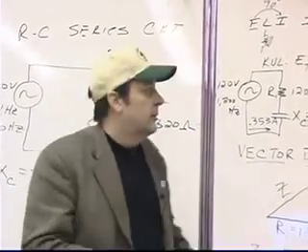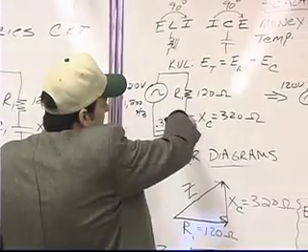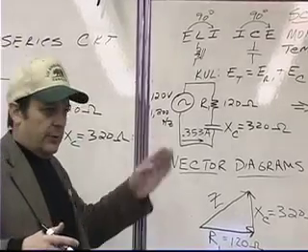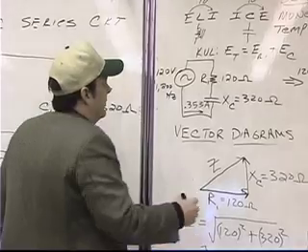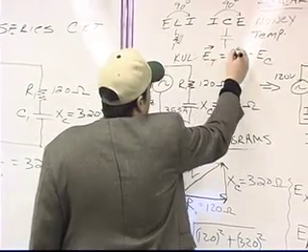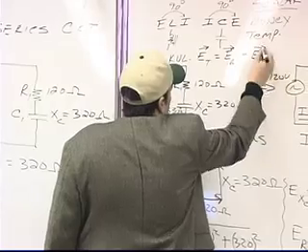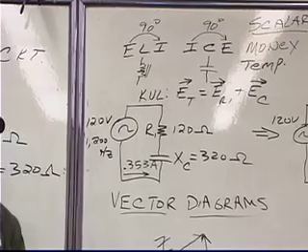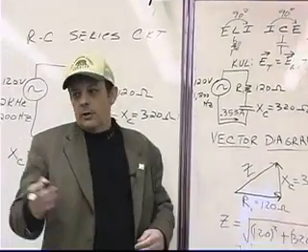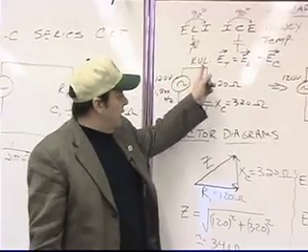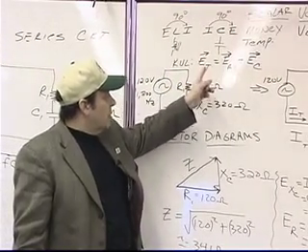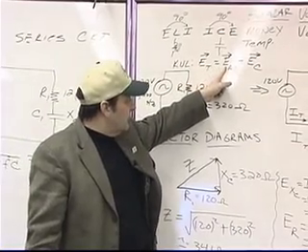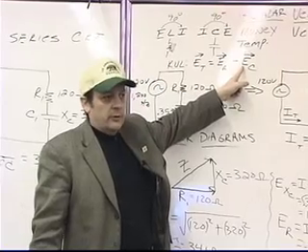That's adding algebraically. When we're dealing with RC circuits where we have an out-of-phase condition, which we see on the oscilloscope that I erased, but I drew in the beginning of the lecture, okay? These have to be considered as what we call vector quantities. And by putting a little arrow over them, we designate the difference between a quantity being a scalar and a quantity being a vector. So basically Kirchhoff's voltage law still applies, but what it says is that the total voltage is equal to the voltage across the resistor plus the voltage across the capacitor.